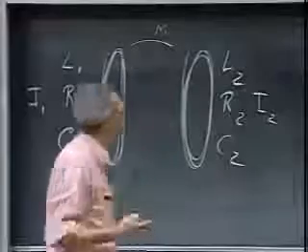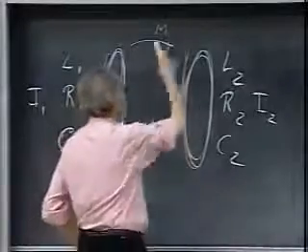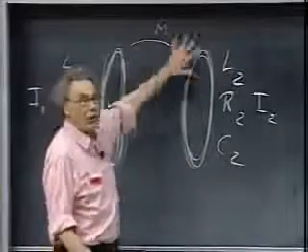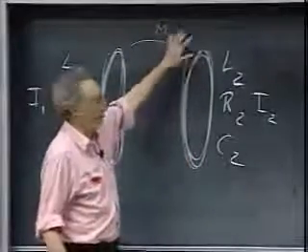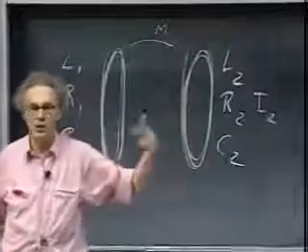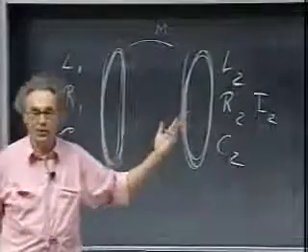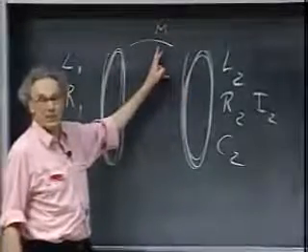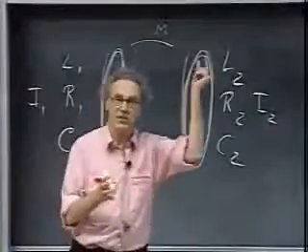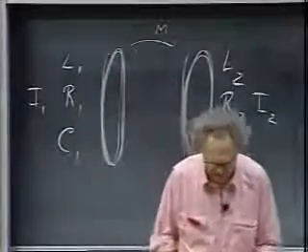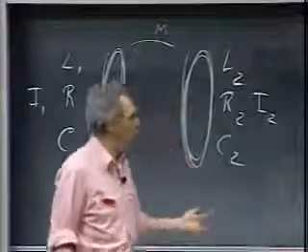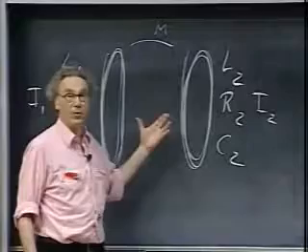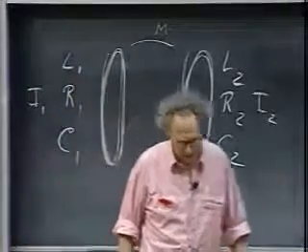And now someone brings in metal. You bring in a chunk of metal. And the metal will experience the magnetic field flux changes. It's AC, of course, always. In the metal, it will start building up eddy currents. And so the eddy currents will change the magnetic coupling between these two loops. And so M changes. And when M changes, you go off resonance, and bingo, your alarm goes off. Clearly, and very unfortunately, this never works for plastic bombs. You must have conducting material that you bring in, so it must be a metal.